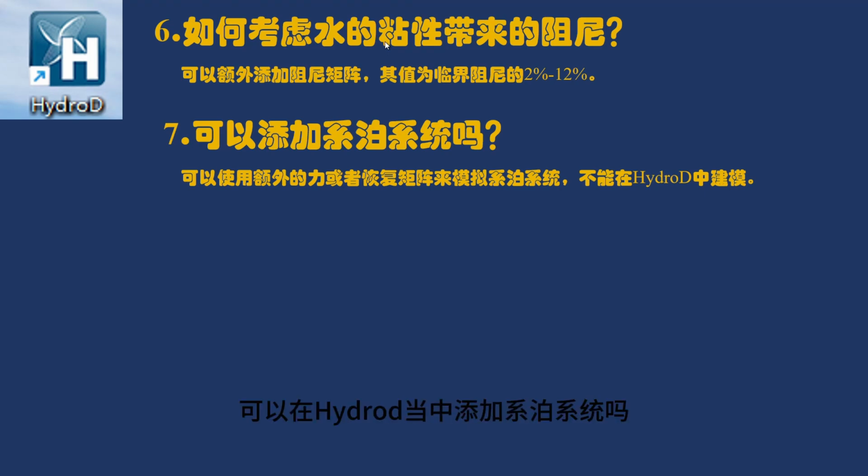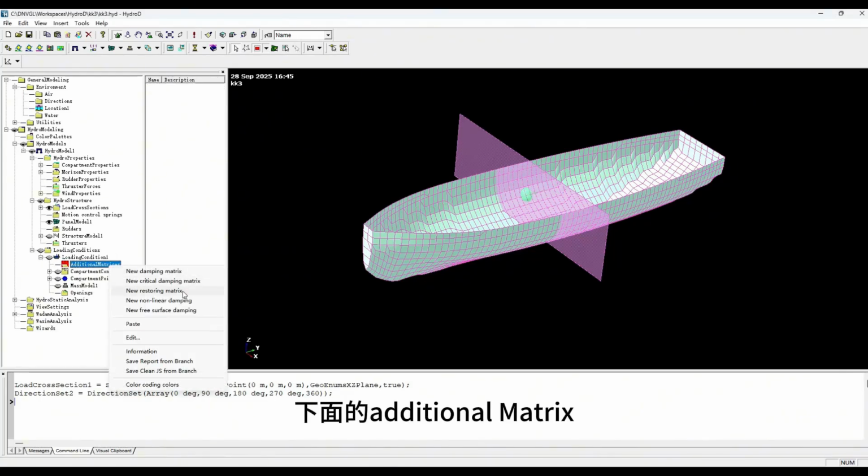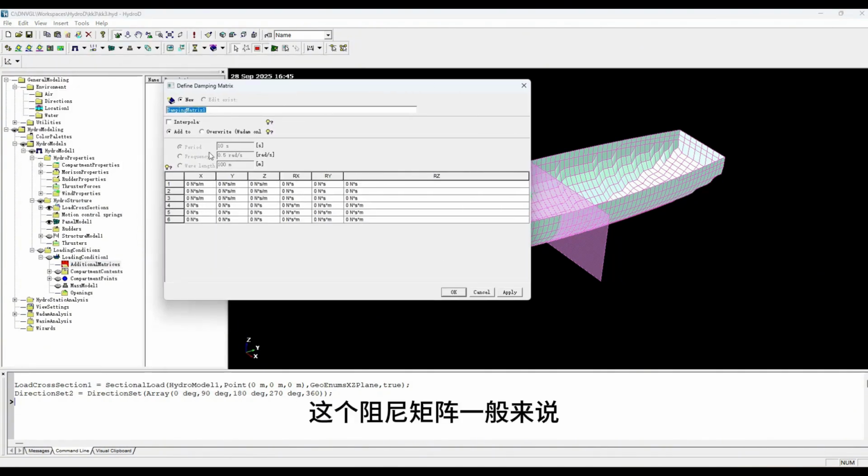Next, can a mooring system be added in HydroD? HydroD itself cannot model the mooring system, but you can use an additional force. Or you can use a restoring force matrix to simulate the mooring system. You can add a damping matrix under the additional matrix option in the loading conditions section. For the damping matrix generally, you only need to input the 6 diagonal elements since they are directly related to the motion of the floating body. This will also affect the results of your response analysis.